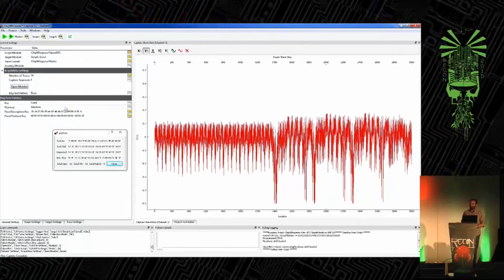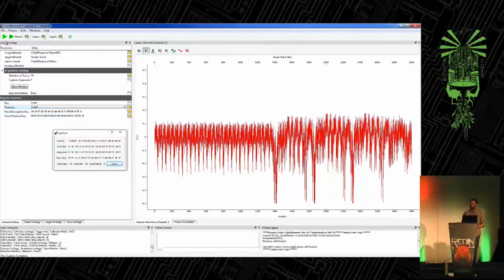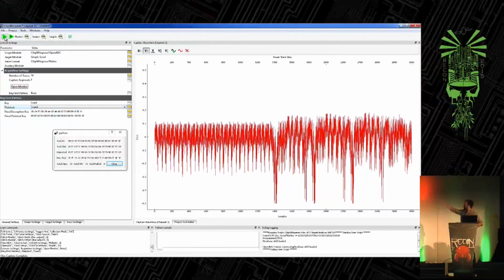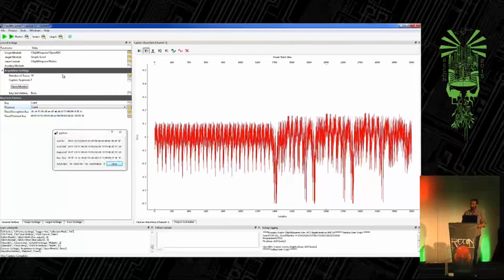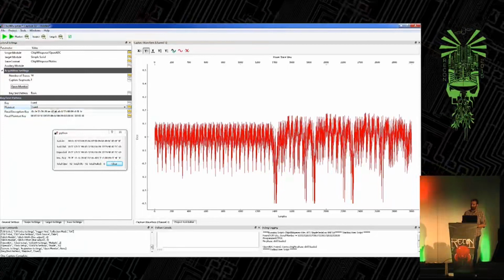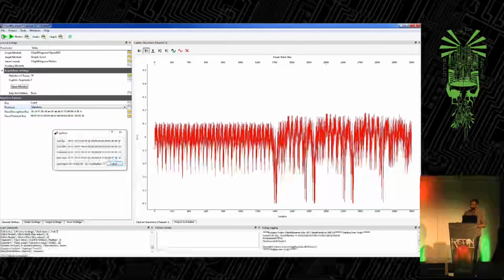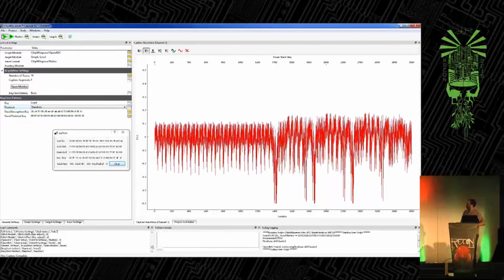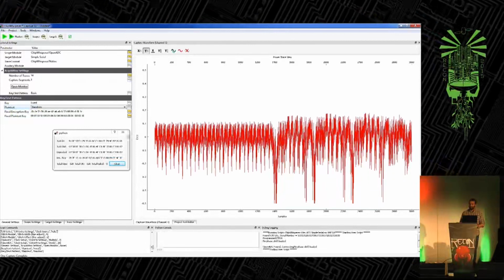To give you a more intuitive feel, if I set this to fixed, so it's encrypting the same data repeatedly, you'll see the waveform doesn't jump around quite as much. There's a bit of noise, but the peaks, if you look at the bottom down here, don't change nearly as much. If I switch this back to encrypting random data, you can see those peaks jumping around a lot more. So it gives you a feeling that there is a data dependency based just on what's being encrypted.